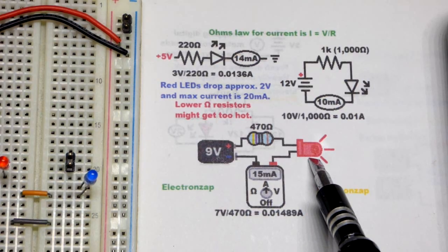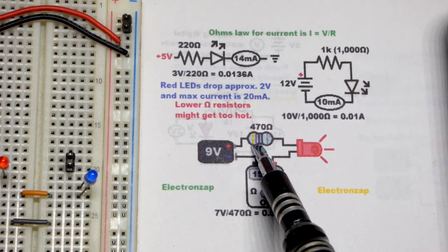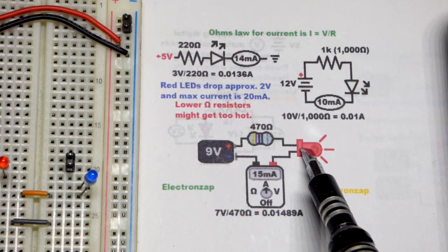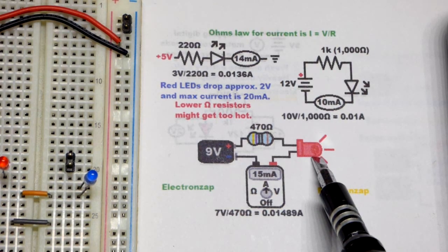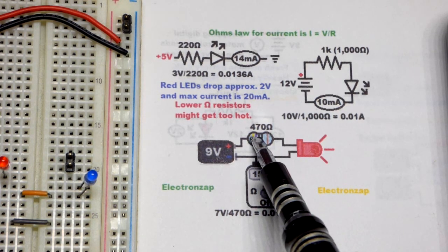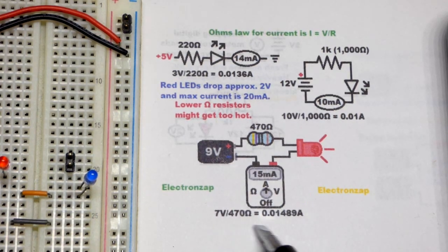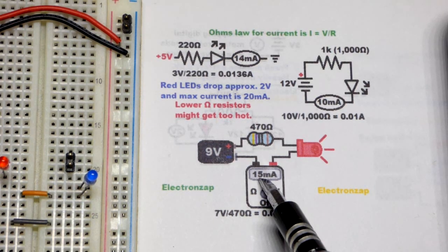The battery is going to light up the LED. You can't do that directly. The battery will fry the LED. We have a resistor to set the amount of current that's going to flow. The LED is going to drop a couple volts because it's a red LED. Blue or green will drop about 3 volts. But in any case, the rest of the voltage goes across the resistor, and based on its resistance, it will set the current. You can calculate that with Ohm's law. You do the math in amps, and then you convert it to milliamps.